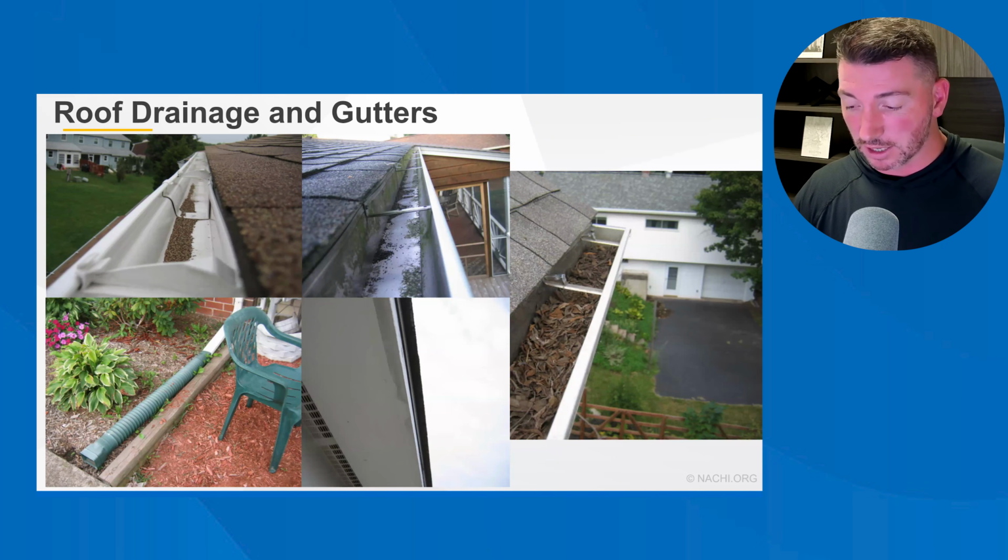Homeowners with conventional uncovered gutters are required to regularly clean out vegetation and debris that get blown into them. Gutters often need to be refitted when severe weather detaches them from the fascia. Roofing gutters may be sloped down toward the downspout. It could be a slope of 1/16 inch per foot or a quarter inch per 5 to 10 feet. This is a general rule of thumb. It's not a building code.